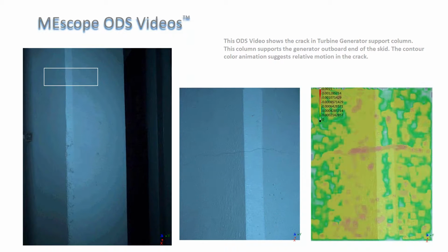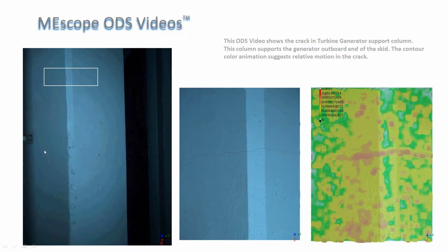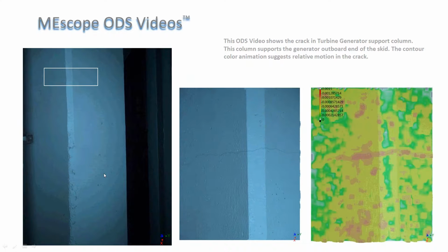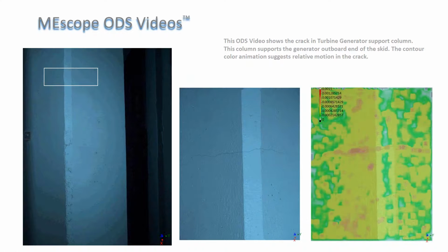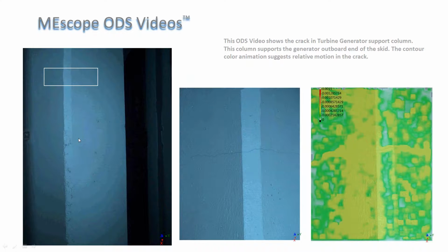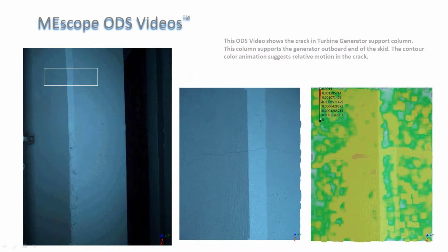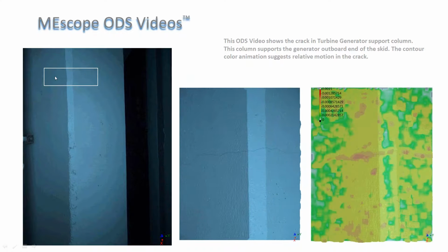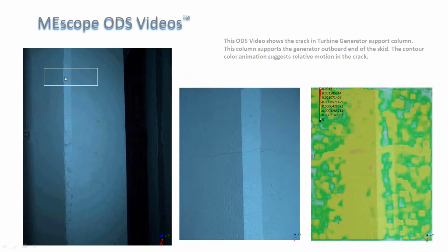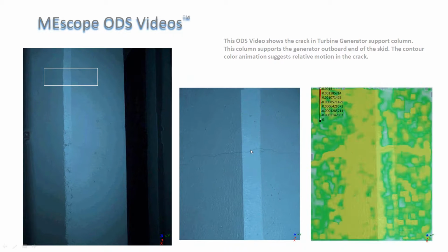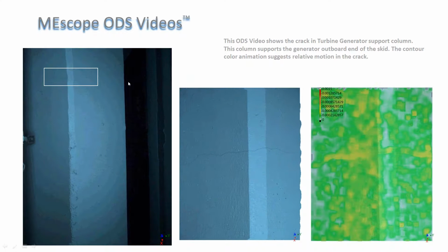So for some reason, something happened to this column, and either it was overloaded, it's slightly buckled, I really don't know. But it was moving ridiculously compared to the other 7 columns. This is a hairline crack, and I tried to show you where it was in the first video here. This hairline crack was 3/4 of the way around this square pillar.